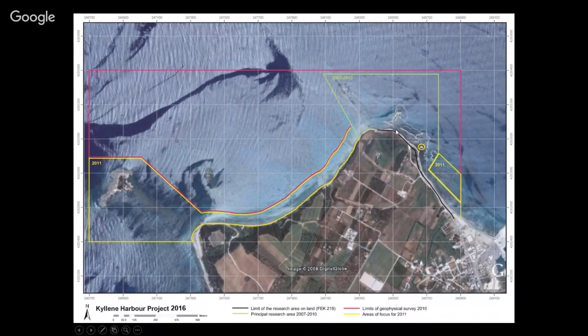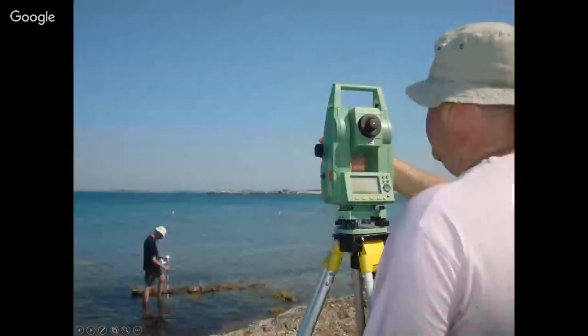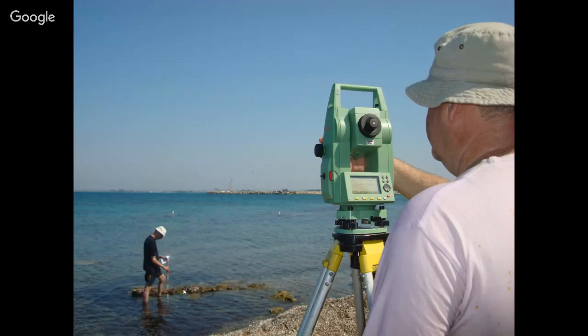We've done lots of other research, such as side-scan sonar and sub-bottom profiling in the parts under the water, but again, I'm not going to go into that. I'll just concentrate on combining the line drawing with total station work and photogrammetry. Most of the walls are quite easy to document. You basically just need somebody who has patience in the water, going with a mini prism over the blocks, because they are in very shallow water, or sometimes even slightly visible above the water.